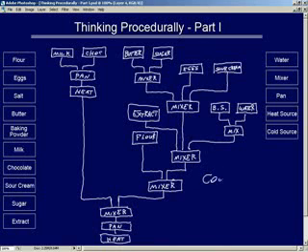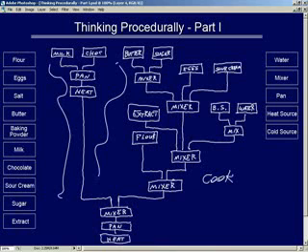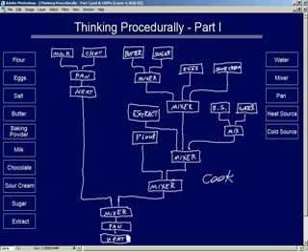That word cook really is important, because in Houdini, when you make changes, it's not like we're constantly solving every single node. If you rotate the screen, it's not like data has to propagate through the entire network every single time. Could you imagine how slow things would get? Everything simply cooks all the way through to the end. Down here at the very end, we've cooked all the way to that point, and there's no reason for Houdini to recalculate or repropagate data through this network unless something changes in the network. Then we can recook it. We'll talk about cooking later, but I wanted to sneak the word cook in there right now because it works beautifully with our recipe analogy and parallels how you work inside of Houdini.